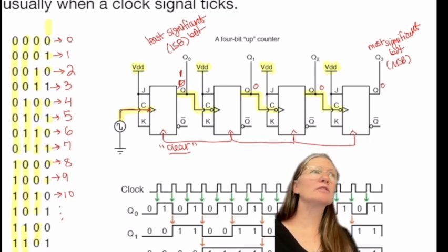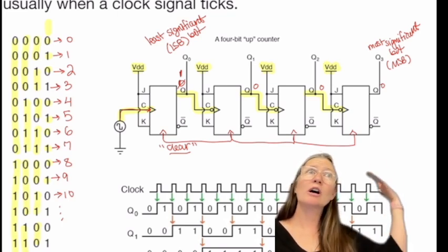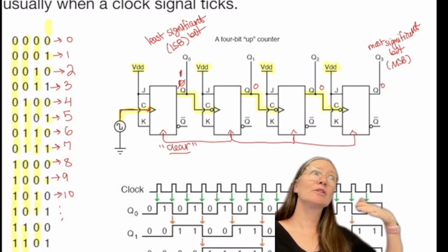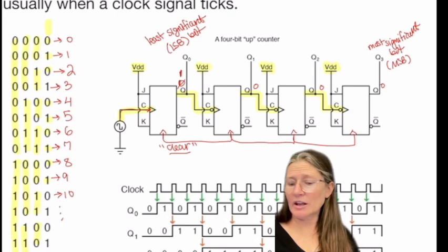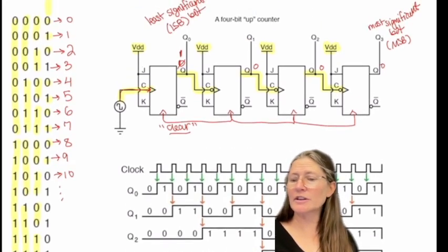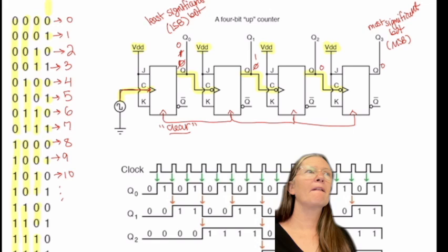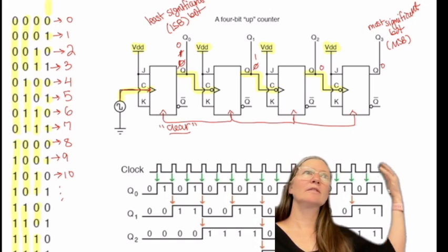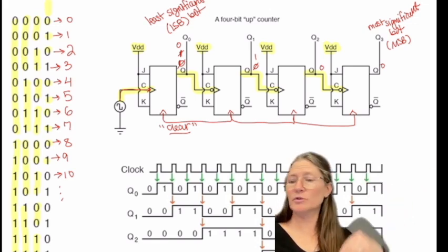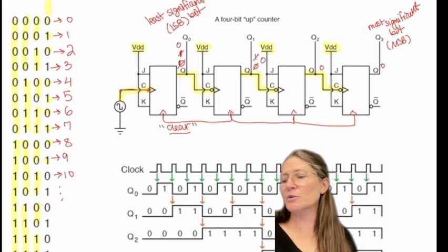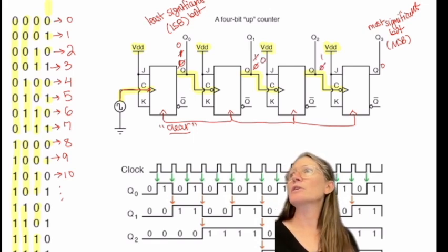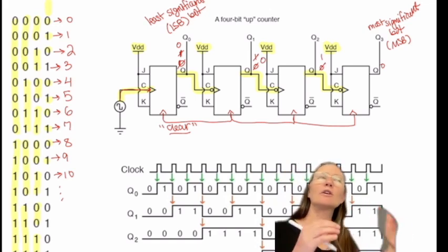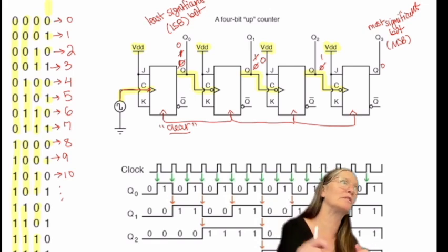But when does it change the next one? What has to happen in a cycle? It goes low, high, and low. So then the next one will toggle after that one changes back to a 0, then this one will flip to a 1. Then that goes 1 again, then to 0, and then it will turn it again, which will then change it to a 0, which then will flip this one to a 1. So that's why there's kind of that delay there. It's got to go 0, 1, 0 in order for it to change.